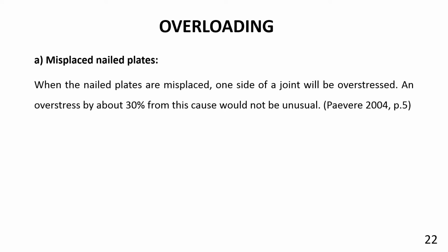Misplaced nail plates. When the nail plates are misplaced, one side of a joint will be overstressed. An overstress by about 30% from this cause would not be unusual.